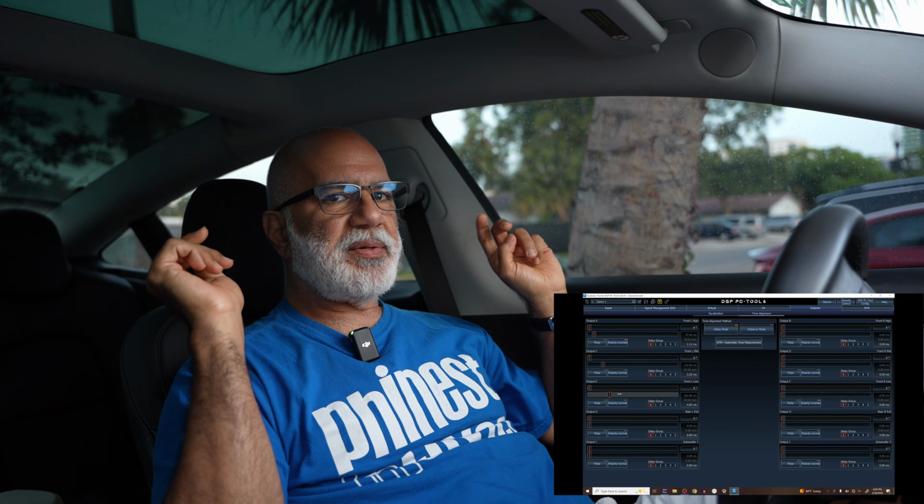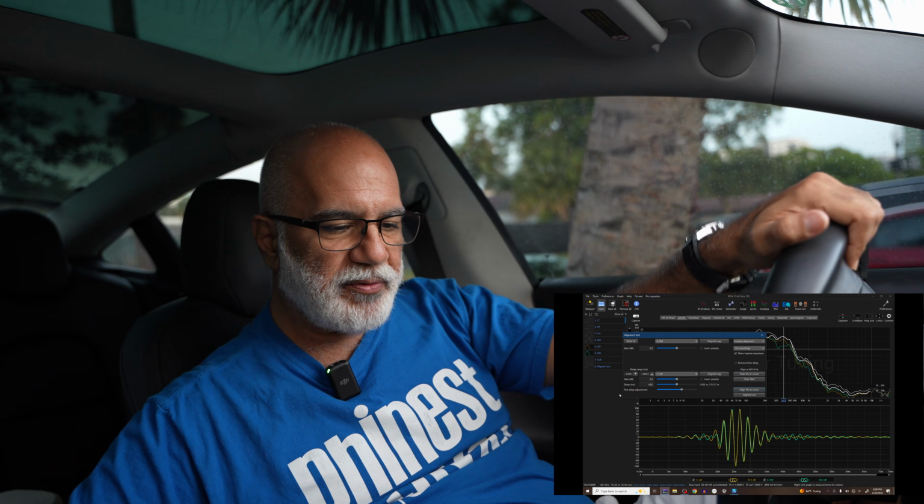Now, since my mids are the ones that are furthest back, I have to push my tweeters back, right? As a pair, I have to lock them and push them back. I'm going to show you how to do that on the Helix DSP, but most DSPs can do this. Let's find the delay first.